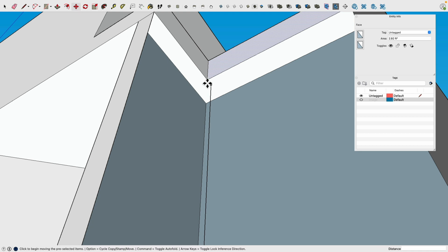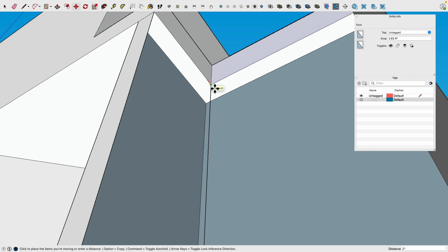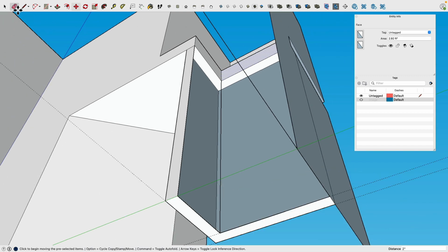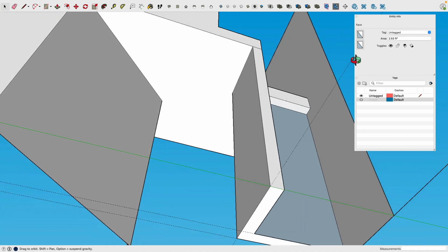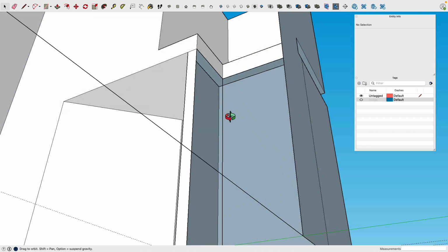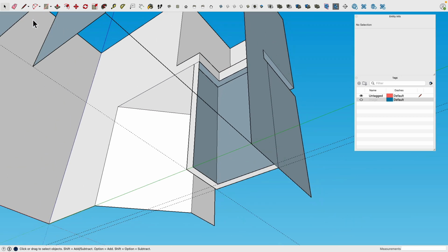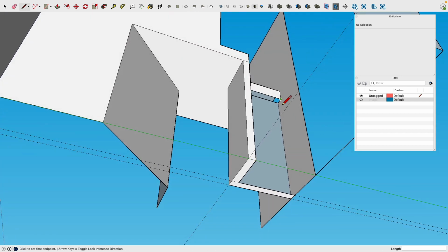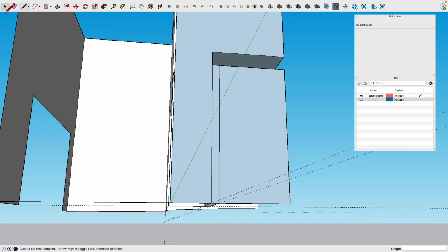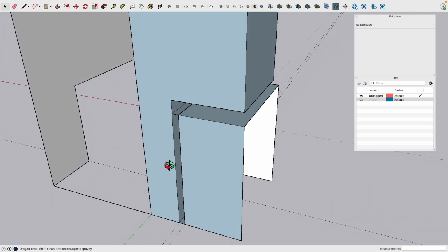So I should be able to move this along the y-axis, x-axis to there. Cool. Then this face I can select and delete. Very good. I will delete this line one more time because if I now redraw it, it should fill it. Yeah, it did. And then also here I do it this way because now I can select this face and delete it.